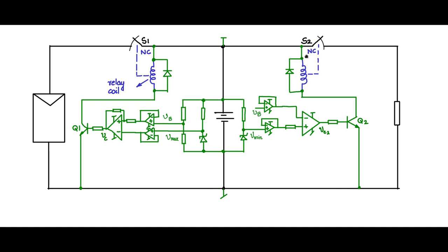That is the logic that we want. And all the electronics here are powered by the battery voltage, so you don't need any extra power supply apart from the battery voltage. If the battery voltage is very large, then you will have to have a small DC-DC converter to generate the power supply which you are using for the op amps and the relays.